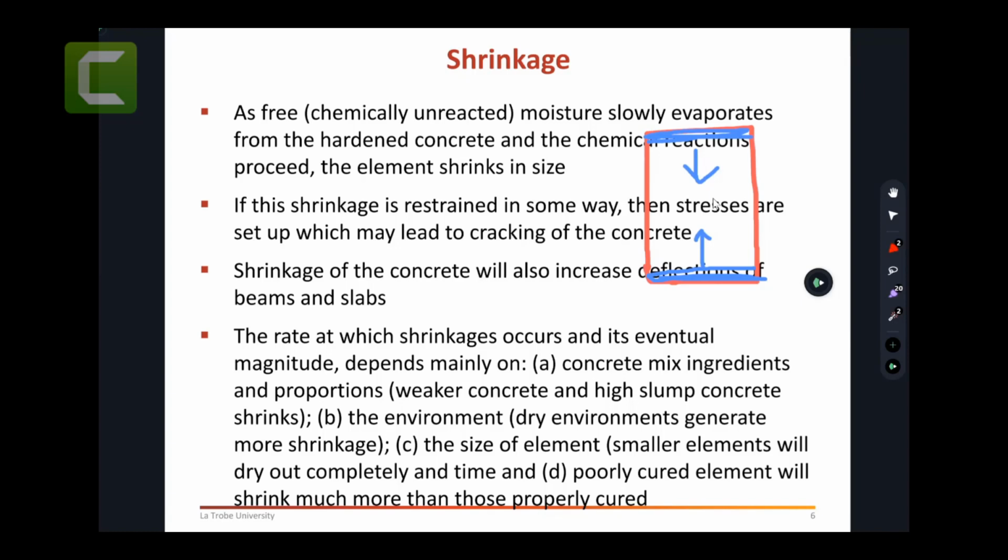Sometimes clients or architects like to have a polished finish of concrete, and they intentionally make a request to have polished concrete. Yes, you're always going to say no. Even if you follow the standards from your end as a designer, you just follow the standards, full stop. Then it's the contractor's role and the supplier's role to supply the correct mix and the correct products. And they also have to conduct the correct curing process. You remember the watering process and all that. So it's a really complicated process.